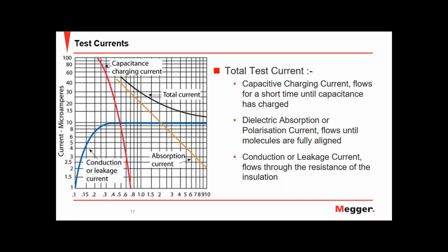So particularly the winding resistance won't affect the PI test. The current that you are using in a winding resistance is circulating through the winding. When you do a transformer polarization index test, the first thing you do is short the high voltage lead terminals, and then also short the low voltage lead terminals, to have everything at the same potential. So really, when you do a polarization index test, there's no current circulating through the winding.